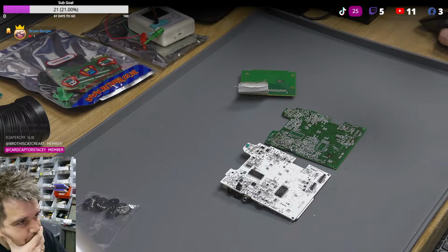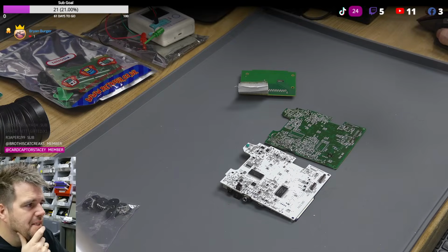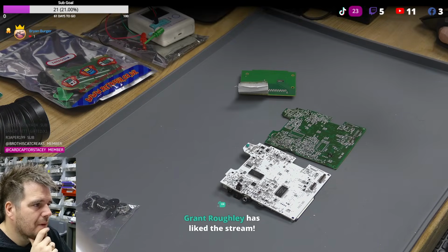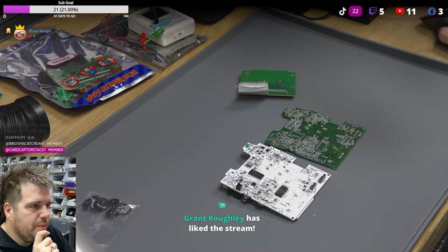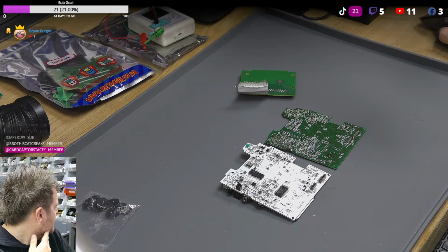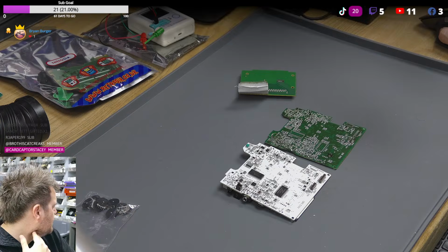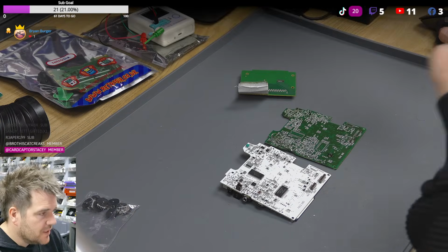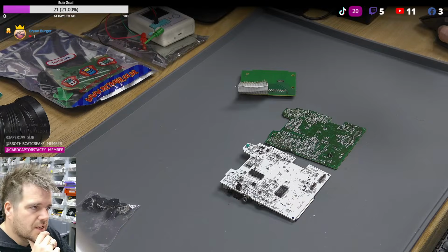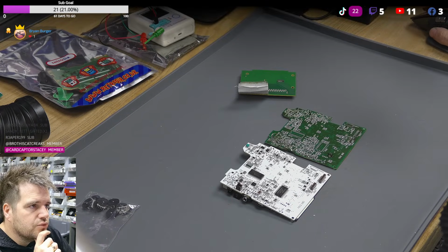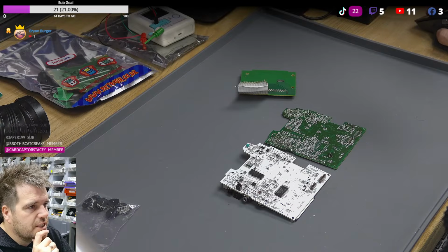So, yeah, there's going to be nothing on the PC Engine schematic. I think it's definitely the power regulation side. 501 was a 6-pin dual. We see the only 5-pin transistors we've got is the epitaxial one we've just identified, so it's not going to be that. Yeah, okay, so I think we're now down to a DigiKey search.